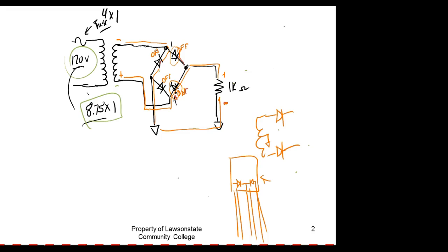So you're going to see a lot of these integrated circuits, these rectifiers, in power supplies. You very seldom see individual diodes anymore. You'll see these, and we'll show y'all some. The ones we've got have 4 leads coming out of it, and two of them are marked AC, and then one is labeled plus and one is labeled minus.